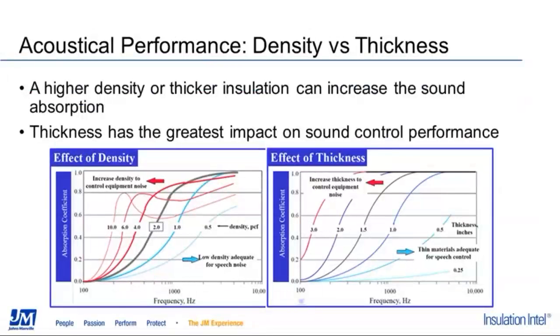So next, we'll look at acoustical performance, density versus thickness. When we look at how density impacts acoustical control, it's important to note that both thickness and density can improve sound absorption. However, thickness will have a far greater impact on sound absorption than density will.